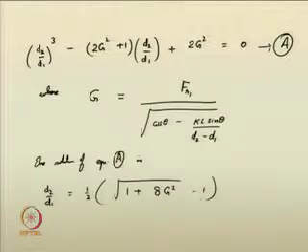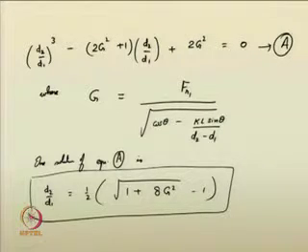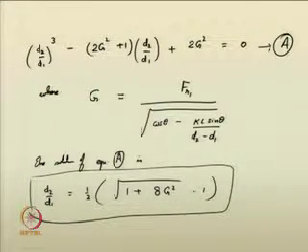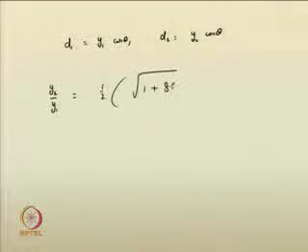So, if this gets clear, you will see that you will get the depth ratio for sloping channels, d2 by d1, in the following form also. Like this relationship, you will get it for sloping channels, as d1 is equal to y1 cos theta, d2 is equal to y2 cos theta. The above relationship can be changed to vertical depth: y2 minus y1 is equal to half of root of 1 plus 8 Fr squared minus 1.